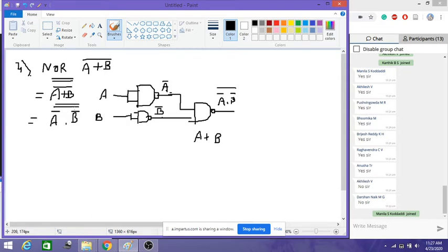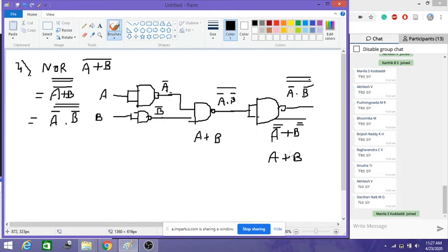So now with one NAND gate we got this one bar. You just apply, once again you complement this because there is one more bar. So that tells you to do one more level of complement. So let's do this one more level of complement here. Then we finally get this as A bar into B bar into whole bar into whole bar. Now if you break these terms, you get A double bar plus B double bar and one more third bar, that is the final bar. So that is nothing but exactly the NOR gate, A plus B whole bar, right?